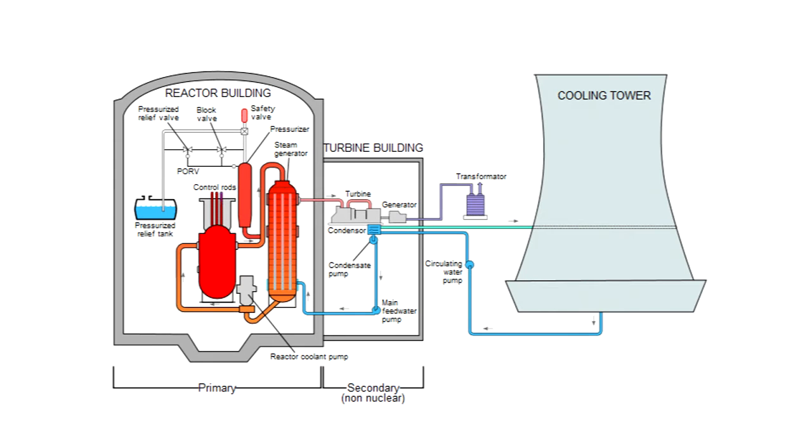8 minutes into the accident, it was discovered that the emergency feed water was not reaching the core because of the closed valves. Operator Faust proceeded to open these valves, allowing the water to rush into the steam generators. It was later discovered that these valves were closed 2 days earlier during a routine test of the pumps. At 4:11 a.m., an alarm signaled high water in the containment building. This is the building where all the water drained from the core through the PORV is stored. In itself, this alarm should have been a clear indication of a leak in the cooling system.